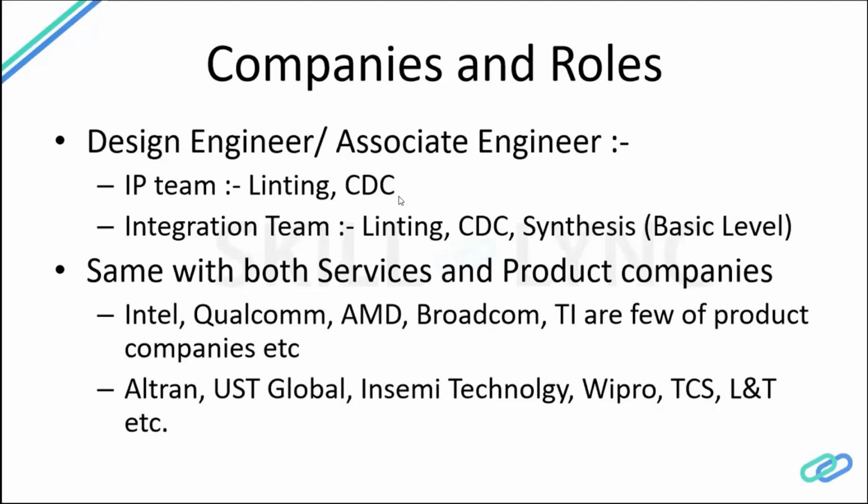There'll be a standard design which is already there. Sometimes you have to comment out some things, you have to add a few things. So we'll make those minor changes and we'll do our linting and CDC checks. If you're joining the integration team, you'll be doing both. You'll be doing synthesis at a basic level. We won't be running the complete synthesis, there'll be a proper full-fledged team for that. As an entry-level engineer, you just run these things to see if you're clean flow-wise or not. Then you can pass it to the synthesis team, which will do the whole synthesis step.